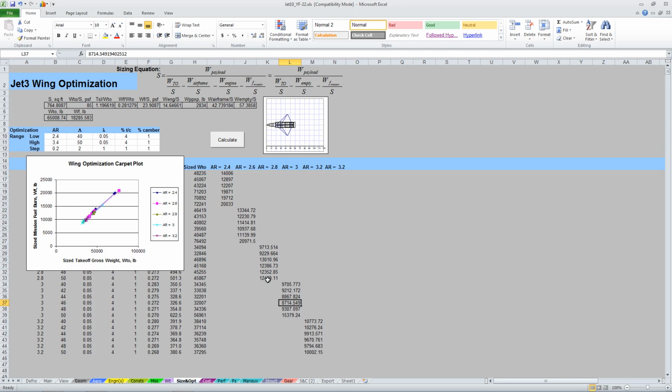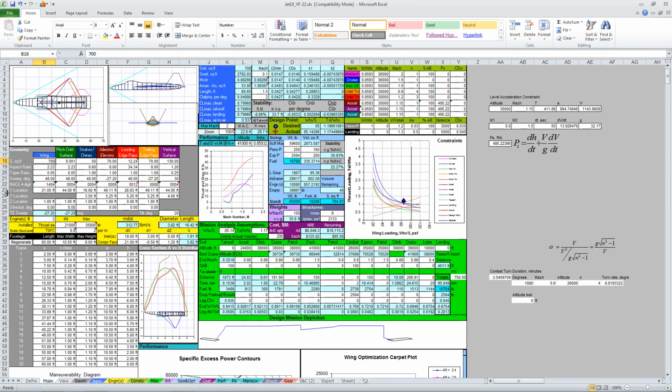If the answer had been 44, we would have had to do some iterations on that because now we can't use that low taper ratio. It'd probably actually be okay at 44, but we just don't want to crowd too close to aerodynamic problems. So it says 46 would be a better sweep angle, so let's try that first. Well, it burned more gas, but it also saved more gas. So I can go to 59.5 now.